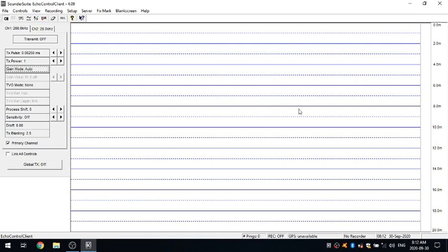It turns out to be a very noisy looking echogram, and you could make it think that you were actually bringing noise in, where you're just amplifying the background noise because the amount of applied gain has been increased so much. If you get into a situation like that, what we would suggest is you increase the processing shift, and that's just an added digital gain for the digital signal processing. So let me just show you an example here.